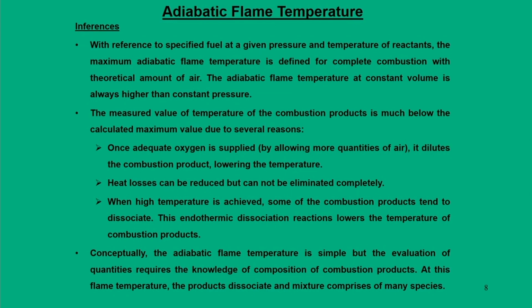If you want to draw certain inferences, what message does it give for a reaction? First, although adiabatic flame temperature is a theoretical number, and in fact it is difficult to achieve in a reaction process, it gives an estimate of the maximum temperature that we can achieve during a combustion process. So, with reference to a specific fuel at given pressure and temperature of reactants, the maximum adiabatic flame temperature is defined for a complete combustion with the theoretical amount of air.